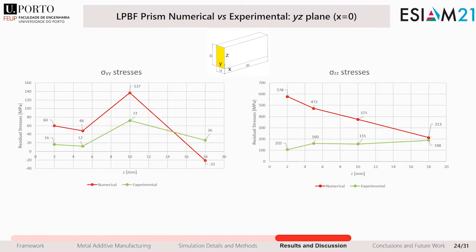For the side face of the block, numerical and experimental results are mixed, but numerical results show the same general trend of overestimation, which may be due to the boundary conditions of the base plate, which was fully clamped in the simulations.